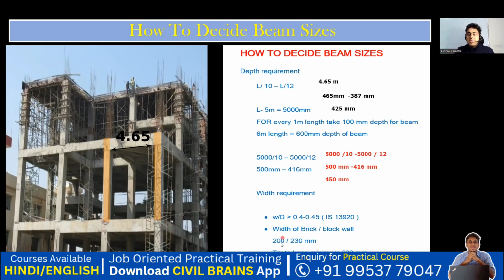So usually, I've written it here. Try to keep 200 mm as the minimum width you're supposed to keep. You can even keep it as 230 mm also. That is what you're supposed to do. Other than that, there is one more thumb rule. Whatever the width by depth ratio is, it should lie between 0.4 and 0.45 according to the Indian Standard IS 13920 detailing code book. You can follow that.